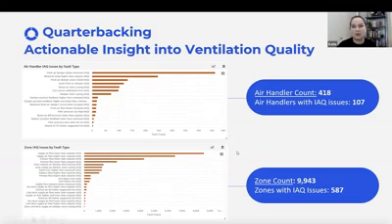But another really big one is our zones. If you have an air handler that's providing the correct amount of fresh air, but half of your zone dampers aren't working, it doesn't matter. You're not getting that air change rate. And that's an even harder one to keep an eye on. We're talking about 10,000 zones across this campus. So to be able to say, hey, look, these are all the ones where my supply flow is lower than my set point, I should probably go take a look at those. And maybe I'll only look at the ones that are 50% off of set point or higher, and I'm going to prioritize and look at those. So it really allows you to take that information and make it actionable.